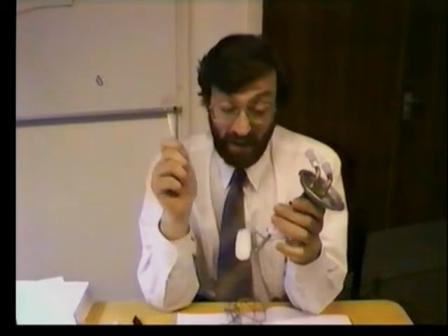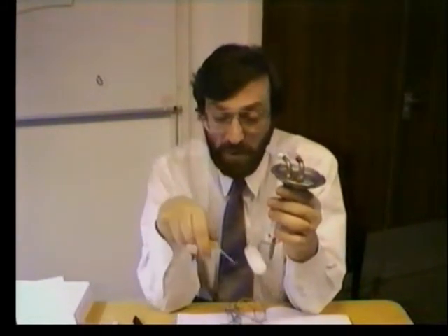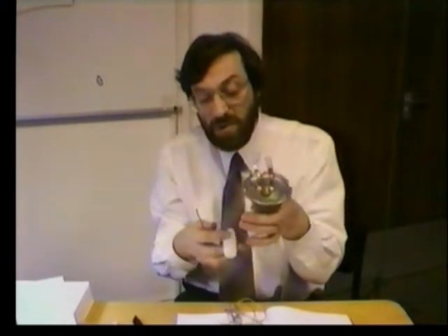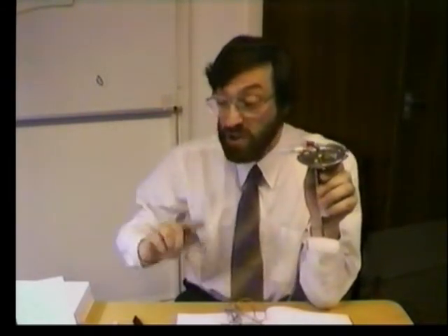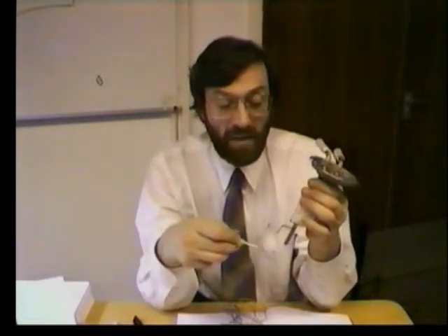Why? We're going to end up in a computer sooner or later, and it's got to do some thinking and number crunching. So we need to know what it is we're measuring. So a transducer converts one measurand into another, and there must be a known mathematical relationship between the two. Still not the whole story though, because even though we've gone from level to rotation, that's still not good enough. Ultimately we're trying to get out an electrical signal, because electrical signals can be turned into numbers which we can get into our computer. So what have we got here?